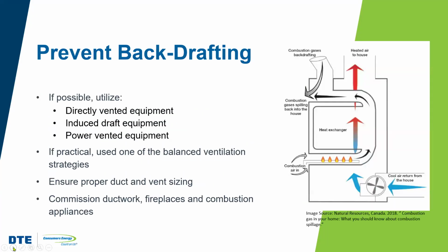We also want to take into consideration in the design of our system the effort to prevent backdrafting, right? Backdrafting is the reverse flow of gas in the flue. So we've got this slight negative pressure that can happen with fuel-fired appliances where we're exhausting out of them out of the building, and so sometimes those gases can be re-entrained into the vent and come back into the living space, and we want to prevent that from happening.